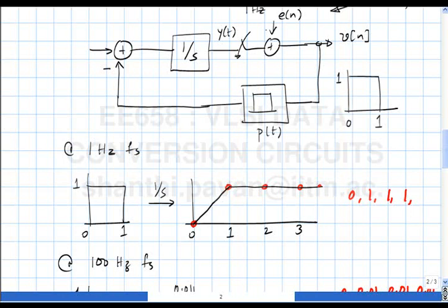What else is there here with dimensions of time? This 1 over s, correct? The input output is dimensionless, so the numerator must have dimensions of, what are the dimensions of s? Frequency, which is Hertz. So the numerator must also have dimensions of Hertz. The numerator has dimensions of Hertz, the denominator has Hertz, the Hertz goes away and you get no dimensions.